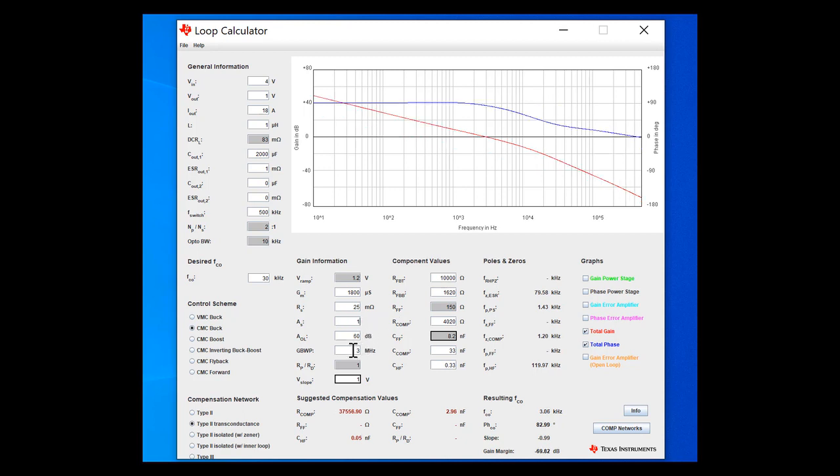Continuing on, the gain bandwidth product and the AOL isn't always all that necessary. It really just determines, is this desired crossover frequency extremely high for you? Down here, we can actually put the slope compensation. What I recommend is just to change this to SLM, which is the ratio of perfect slope compensation. So 1 here will give you the perfect slope compensation you need for the design.